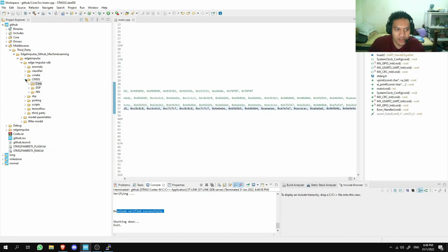And then, how the coding works is that this is the middleware. You need to make sure your middleware is over here. My bad, how the CMSIS-NN is applied is through the middleware over here. If you open the middleware, you can see there is the CMSIS-NN over here, that is the neural network. Basically, we need to make sure this middleware folder exists, so that we can use the neural network CMSIS library for our milestone.